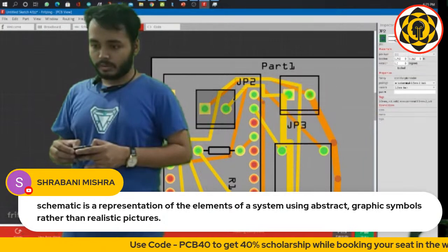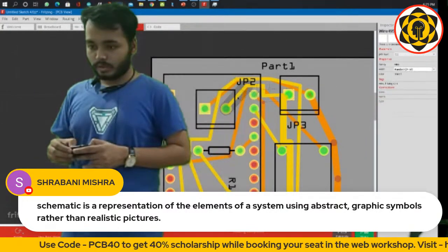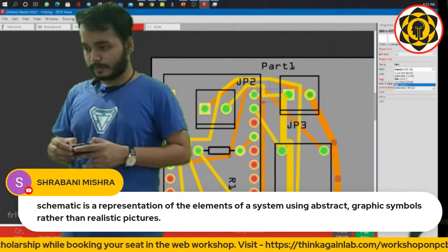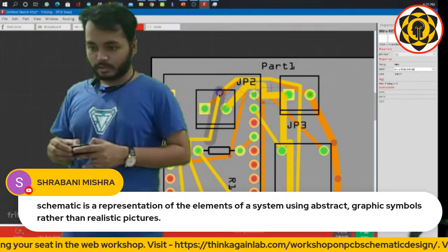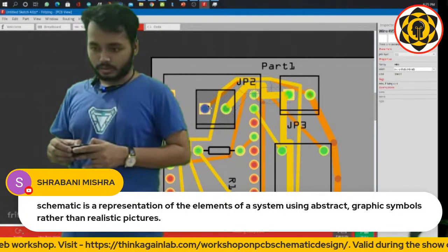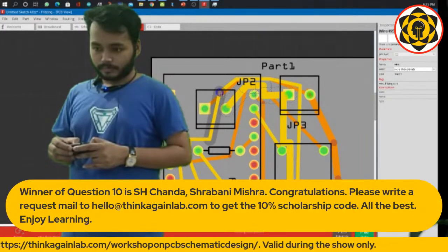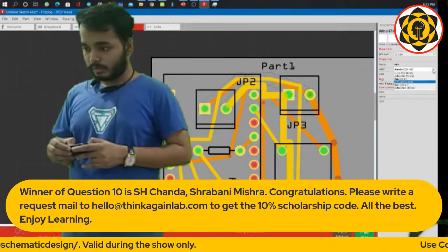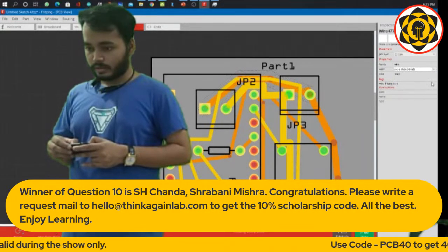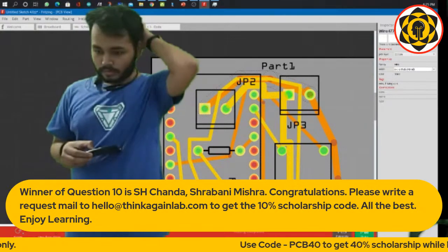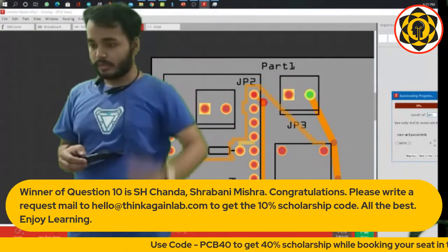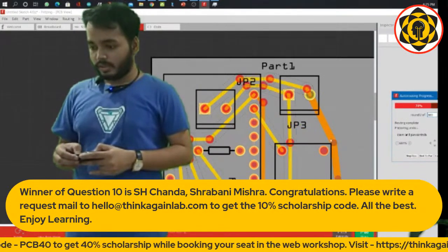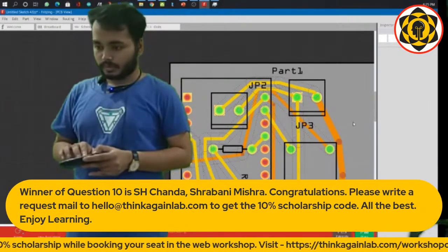Okay, this is the one connecting to there. This wire and that wire will be increased because those two are shorted out, so you need extra thick. This wire, another orange one, that's the one. You need extra thick. All of the wires are done. So I'm going to auto route once again, just to maintain the space, since I have increased that distance.